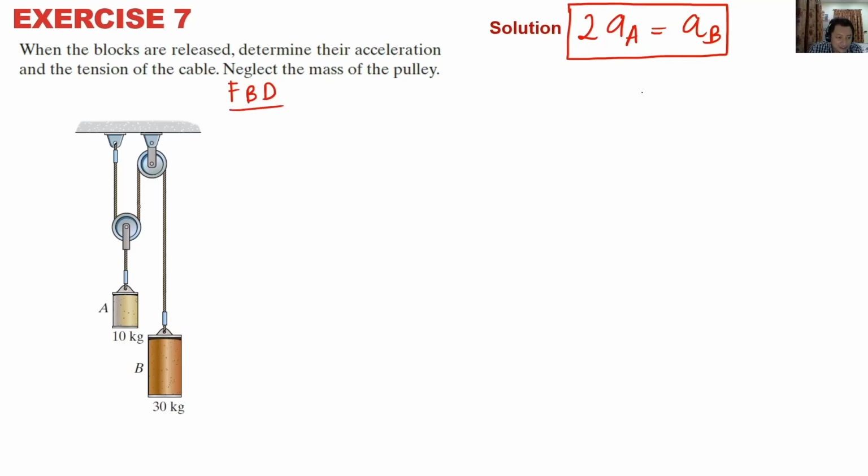So when you do a free body diagram and you see things like cables, you have to cut them up. When you cut them up, you will see that the location where you have cut them up, that location will be tension, tension, and tension. So now, we need to isolate the bodies. So let's isolate the first body, which is body A.